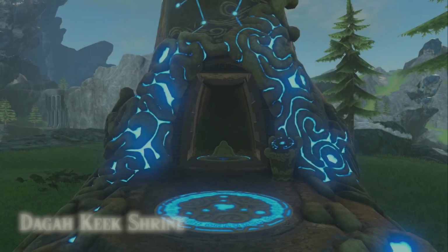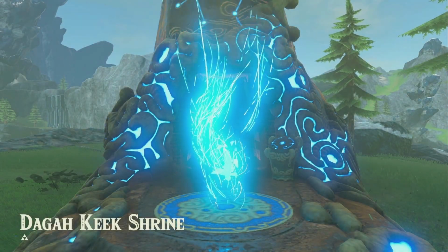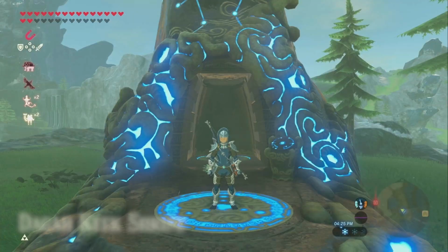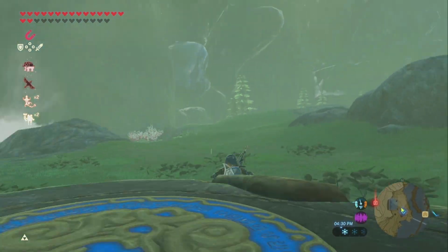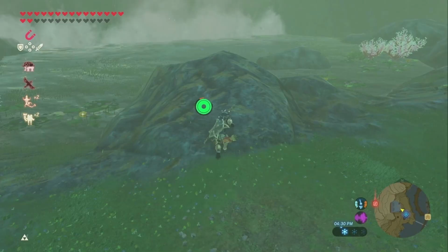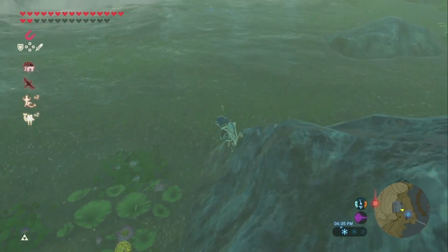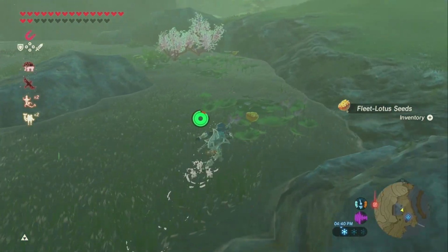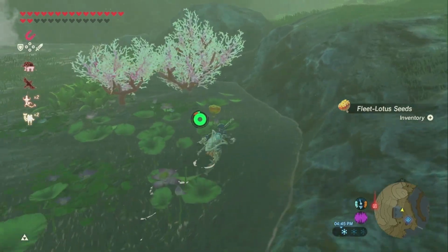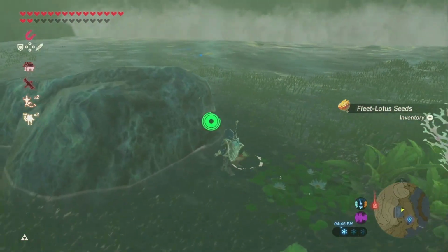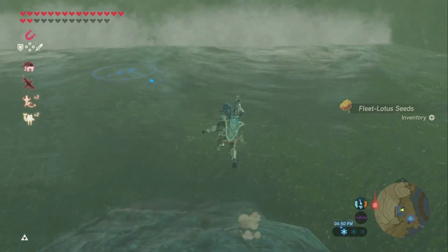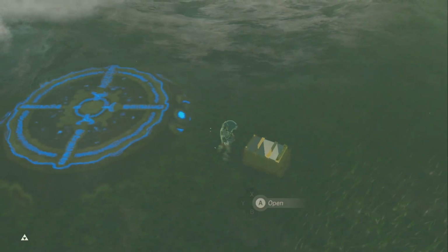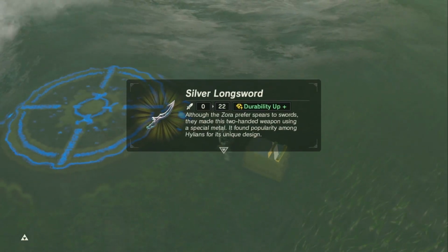Strategy: many water heaters have hot and cold connections stamped onto the top of the tank. You can trace the piping to see which pipe is going into the cold. However, you can't make any conclusions based on this. On most water heaters, it's very easy to take the dip tube out of the cold inlet and put it into the hot. Many installers don't do this because it's more convenient, given the orientation of the pipes and the tank. It's best to operate the system and see whether you run out of hot water very quickly. Unless there is a problem with inadequate hot water, the dip tube is probably in the right place.